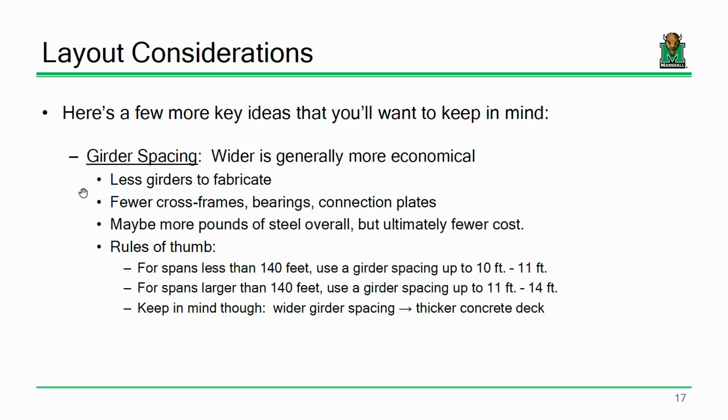So I'm going to give you one hell of a strong suggestion on your project and say you use 4 or more. Now, that's if you're talking about, let's say, a composite steel I-girder bridge where you have a concrete deck and steel I-beams. If you have a shorter span and you want to use a hollow core slab or post-tension segmental boxes, the cross-section is different. So, we can discuss that when we get there. But that depends on what you use for your span.